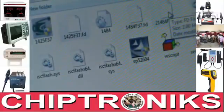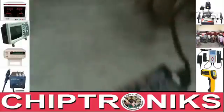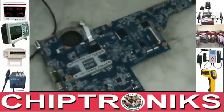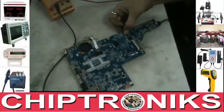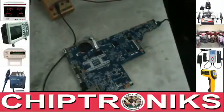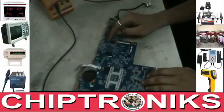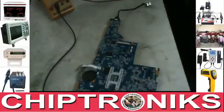Now what you need to do, first you remove the BIOS IC from the board, and then you take a backup and check which file size is present inside this BIOS IC. Then you decide which file you need, 1 MB, 2 MB or 4 MB. Here first I remove this BIOS IC, and then I program it with one file. Then we check whether our motherboard works fine or not.